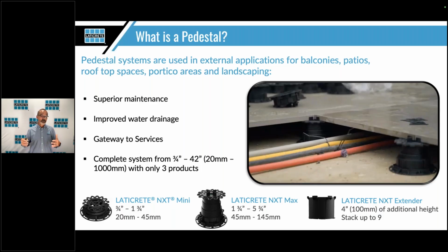So if you've got conduits and stuff running around, you can get in and maintain them. You don't have to worry about them being poured in concrete and boring underneath if you ever had to redo something. If you're pouring new and you want to have more grade to the drains, a little more slope, to get the water out of there quicker, you can do that because you don't have to worry about ADA. You don't have to worry about people transitioning back and forth or how it affects other people when they're walking on it.